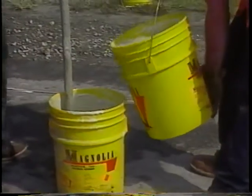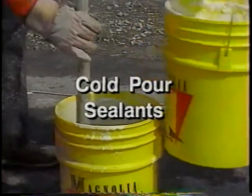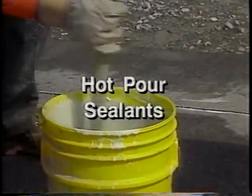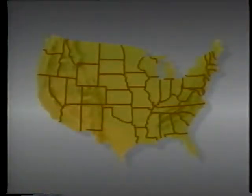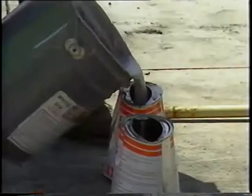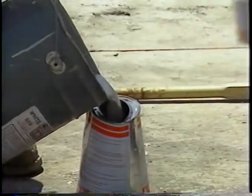Sealant applications are divided into cold pour sealants, such as resins and epoxies, and hot pour sealants, such as hot pitch and asphalt. Most states specify which sealants work best under their particular climate and geographic conditions. There are 3 common methods of applying sealant which appear to be equally effective.